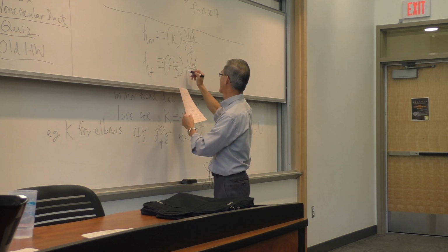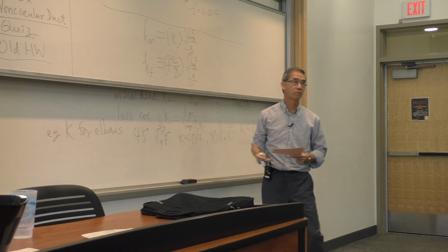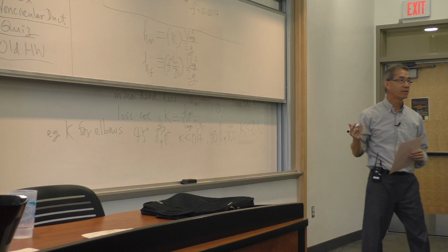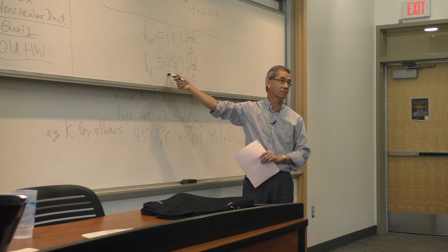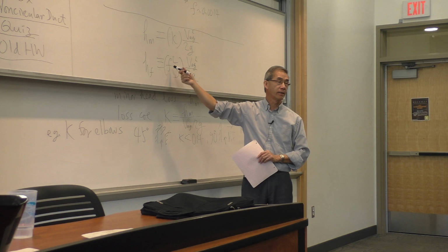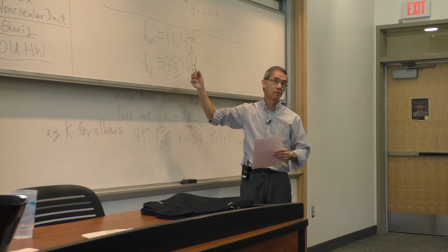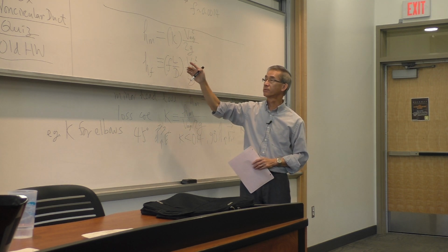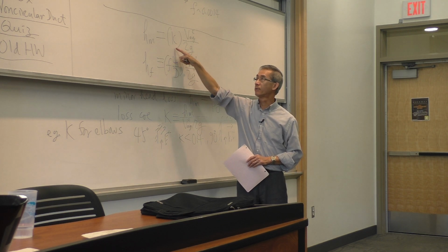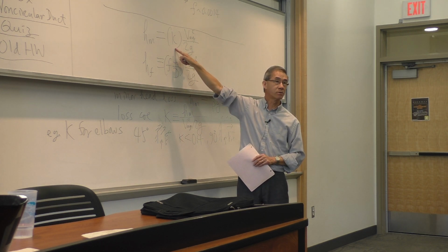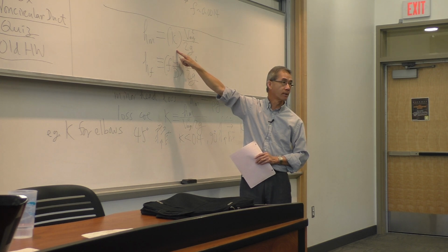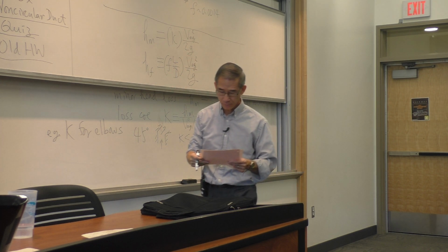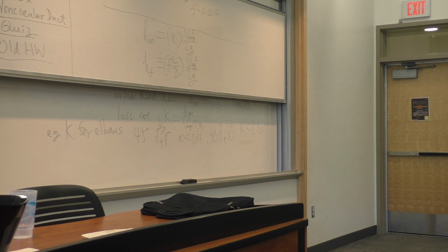As a contrast, the parameter is the difference. The Moody diagram frictional head loss resulted in the use of friction factor and the length over diameter. Now, due to separation of flow, not necessarily just shear stress, all that now is replaced by a dimensionless coefficient called loss coefficient. And that has to be provided and is problem dependent. Okay? So as an example then, with all the components